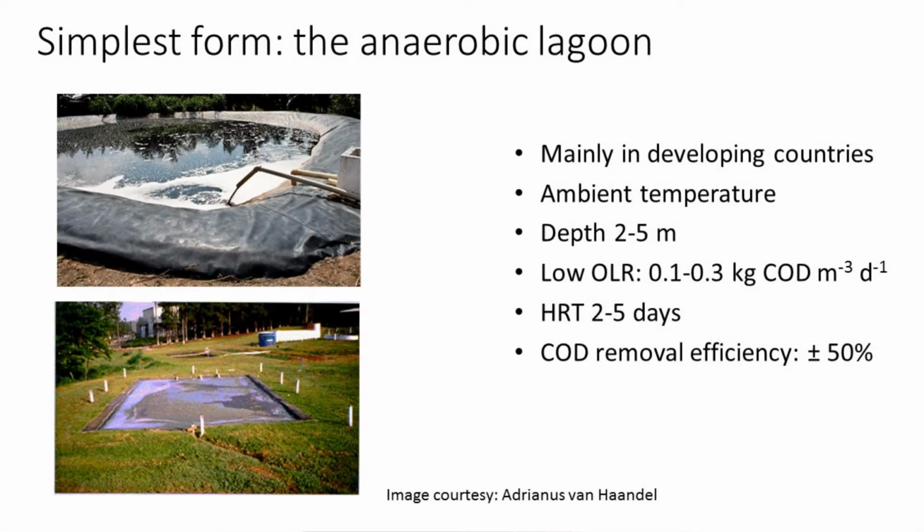Again, it's a choice. Is there necessarily in the reactors or in the engineering a best choice? In my opinion, no. It's very location dependent, and it's also dependent on who sells you the reactor and the system and the local expertise available. So when we now talk about reactors, we're not going to talk about some specific best solution. The simplest solution, maybe this first one that I discuss, may not be the best solution. It is typically not a good solution, but it is the cheapest solution: the anaerobic lagoon.